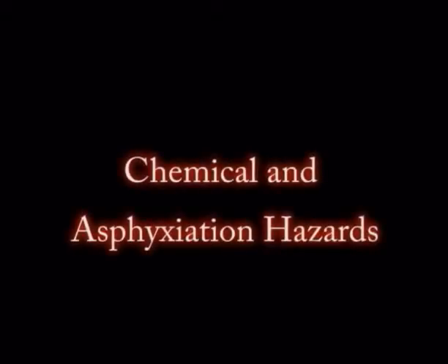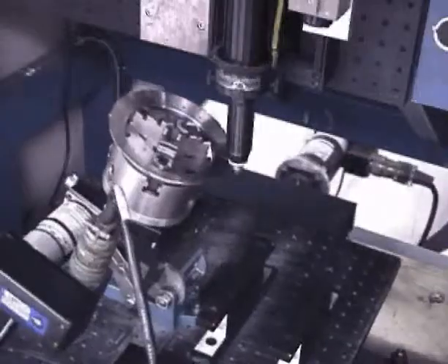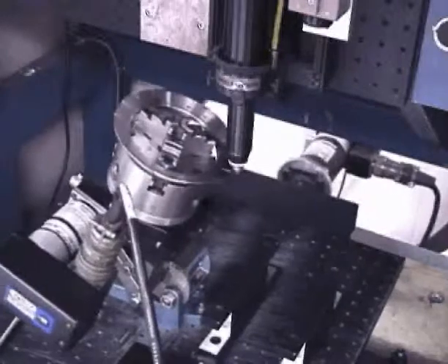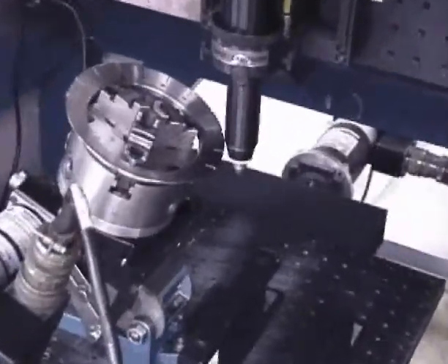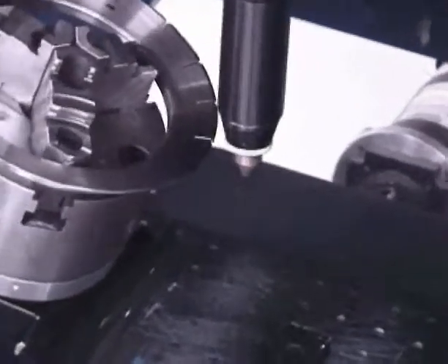Reactions induced by lasers can cause hazardous particulate and gaseous byproducts. An example of this occurs in material processing such as laser welding, cutting, and drilling from a high-power CO2 laser, like the Coherent Diamond laser. The vaporized material can create potentially hazardous fumes and vapors and can quickly lead to asphyxiation in a closed room environment. General ventilation safety procedures should be used when lasers are used in this manner.